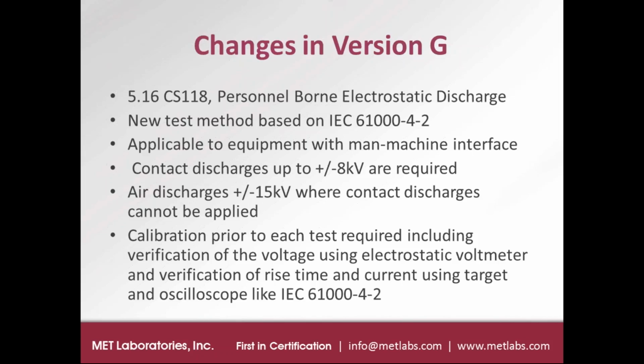So for this presentation I'm using my laptop computer, and the majority of the surface of the laptop is plastic. So if I was going to perform an electrostatic discharge test on this laptop, I would mostly be using air discharges to see if the tip would discharge through the small openings around each key on the keyboard and on the mouse pad and things like that. Whereas if you're testing an electronic chassis that's going to be mounted in the deck of a ship or something, it might be all metal, so you would mainly be using contact discharges with the sharp tip right to the metal chassis of that device.